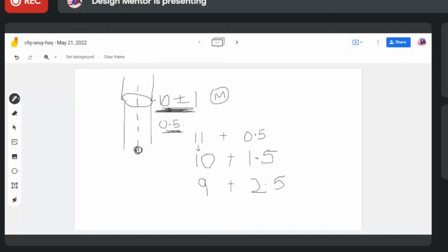The hole cut out for the screw will always be a little bigger than the screw's diameter, because there's some additional tolerance they've given. Screws sometimes might get manufactured a little big, but still it should be able to fit. In the same way, all the parts in lots of components are manufactured so that if one component gets a little bit bigger or smaller, it should still be able to fit with the others. That is why size and position tolerances are important.